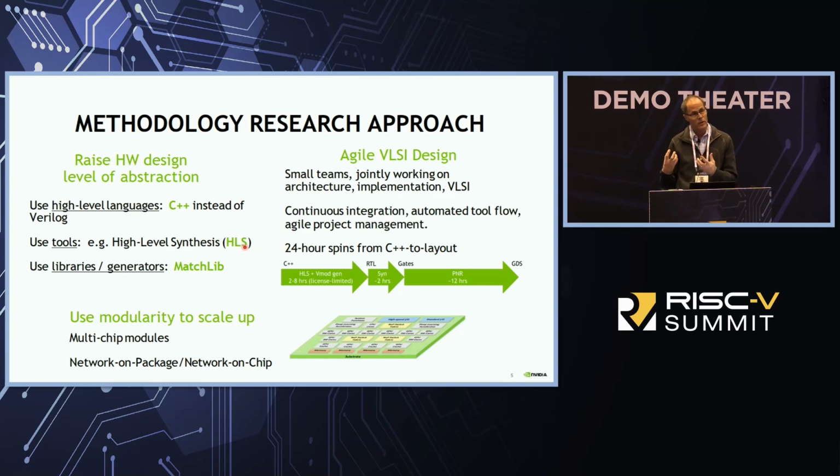The idea behind high-level synthesis is that you're developing at a significantly more abstract level than RTL design, which is the prevalent design methodology in the semiconductor industry today, where you're writing Verilog RTL, tying every operation to a specific clock cycle over a span of time. In high-level synthesis, you're not tying every single operation to a specific clock cycle, and you're leaving it to the tool to figure out the optimal implementation.